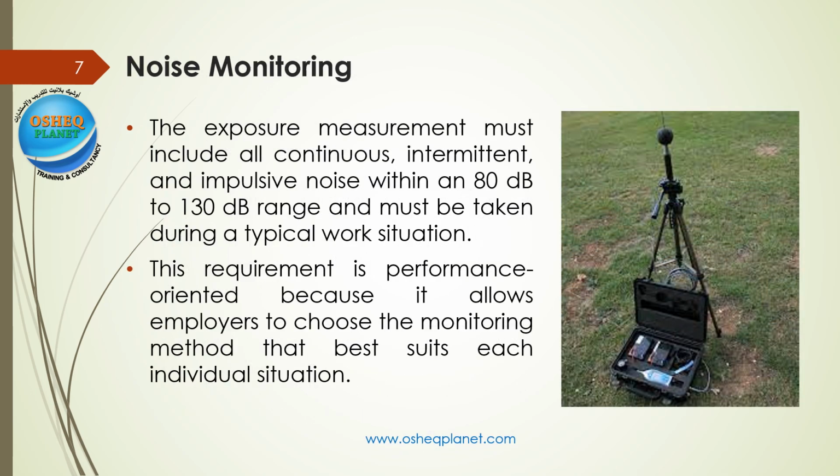The exposure measurement must include all continuous, intermittent, and impulsive noise within the 80 decibel to 130 decibel range, and must be taken during a typical work situation. This requirement is performance-oriented because it allows employers to choose the monitoring method that best suits each individual situation.